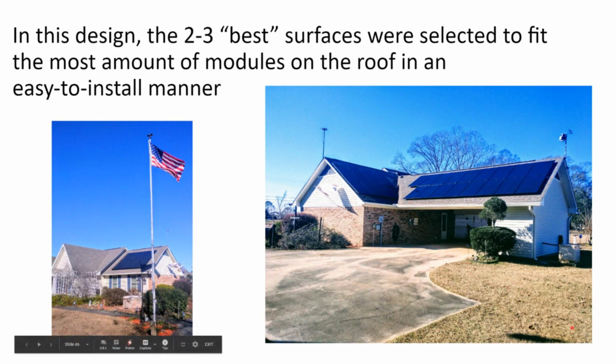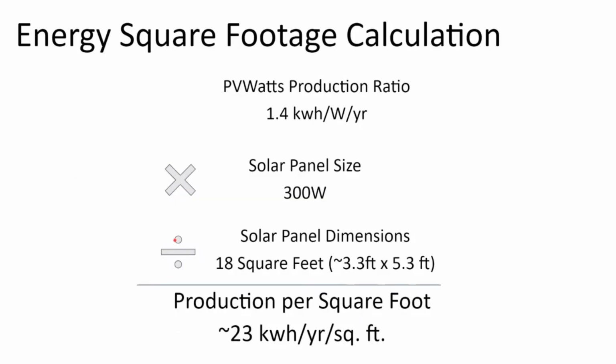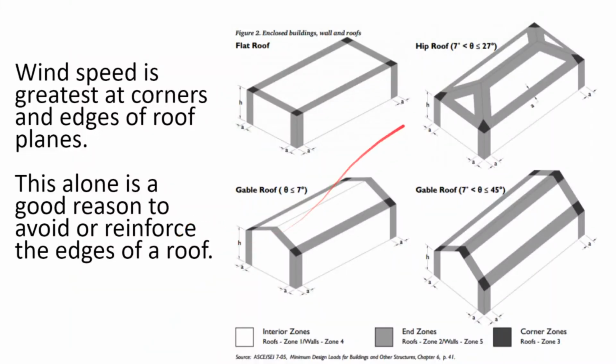Even a slightly larger offset has benefit. A 4-foot offset gives the installation crew even more flexibility if encountering unforeseen roof obstacles or structural issues. The further away from the roof edge the solar array is mounted, the easier it is for the loading on the roof.